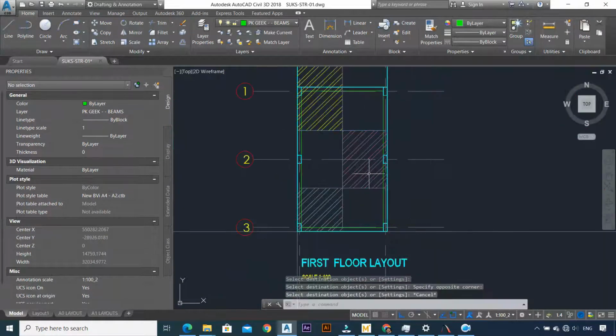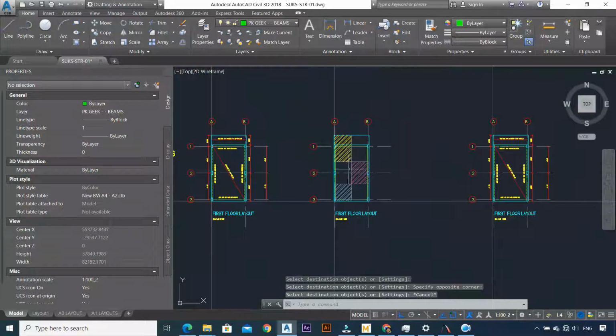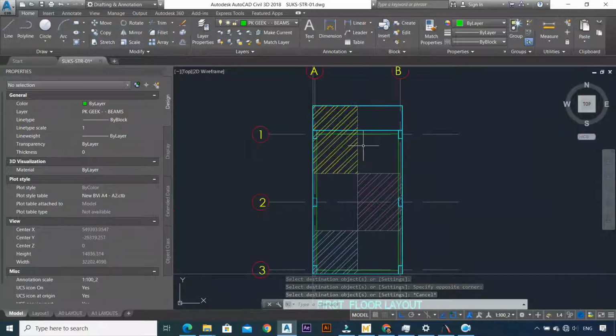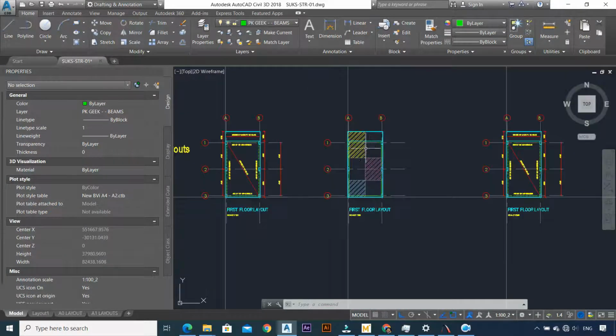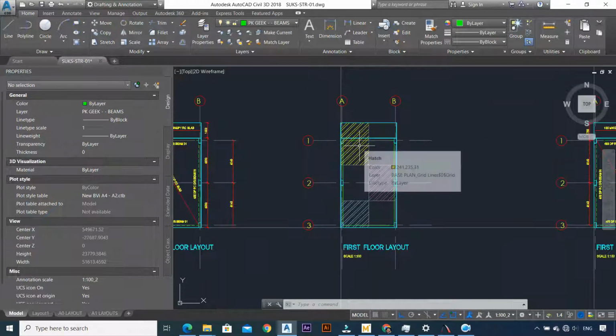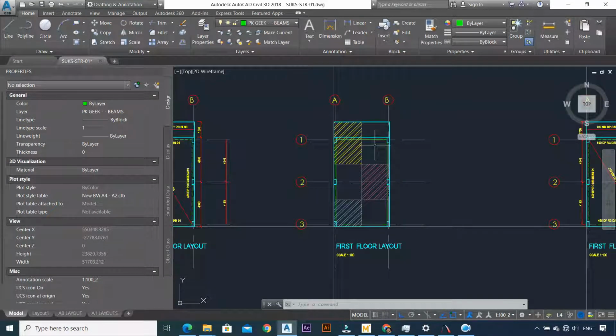Anyway, just take time to revisit the video, see how I created the tributary areas. But it's as simple as that. And this is why a lot of people, as I was telling you, prefer to use lunchbox buildings, because with lunchboxes, as you can see, the tributary areas are quite easy and you don't have to worry yourself too much. So the principle is go to the center.